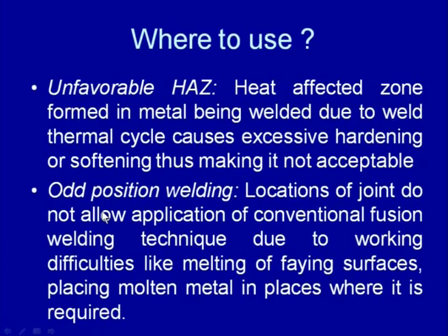And further, the brazing, soldering and braze welding processes can be effectively used in odd position welding, which experiences a number of difficulties because the locations of the joint where the common fusion welding processes are not favorable, due to working difficulties like melting of the faying surfaces or placement of the molten metal in the desired location. Then brazing and soldering can be effectively used because it requires first heating of